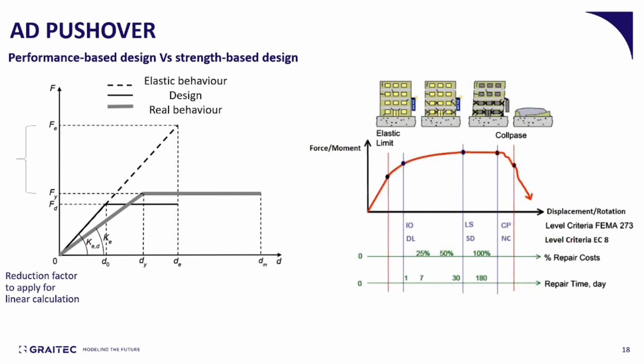At least give some time to the people that might be inside to leave the premises, so we don't have injured or dead people. So in this case, we allow the design to be on this part of the curve. And in the last case is the structures that we don't mind at all to collapse in case of an earthquake, so we design them at this part of the curve.